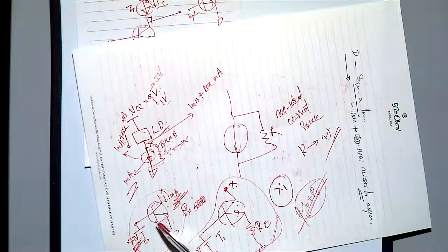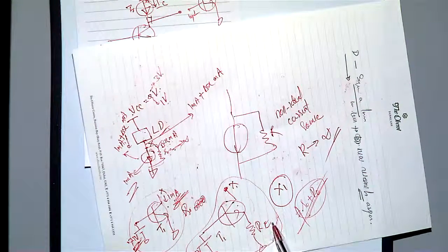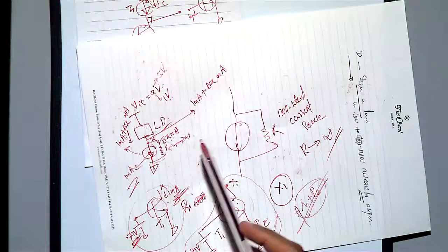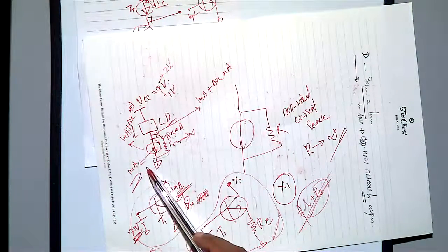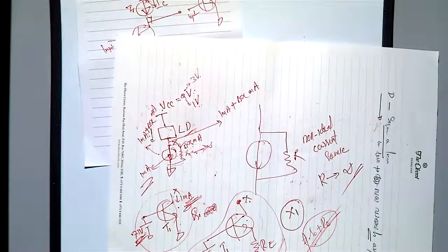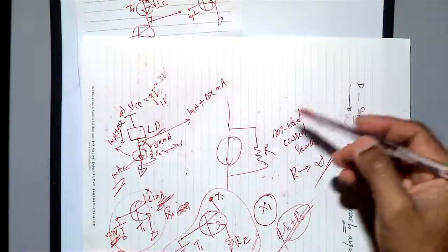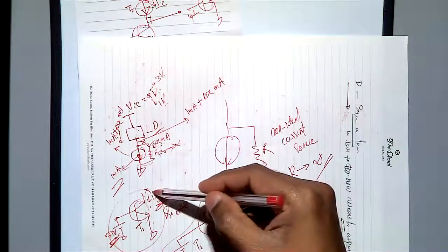So that is one technique. So you can increase the impedance of the current source by using another RE here, which we already studied. When we connect an emitter degeneration, actually we are increasing the value of RO, the output impedance. And then we can use that in the current source scenario, so that you can make the current source closer to the ideal value. Or another way of explaining is when you have this RO for this particular one,